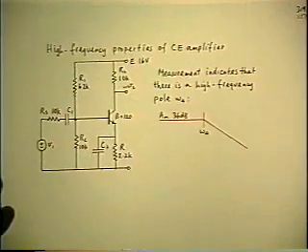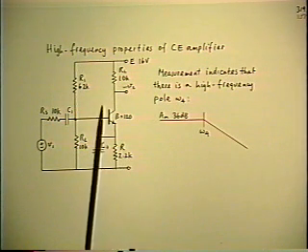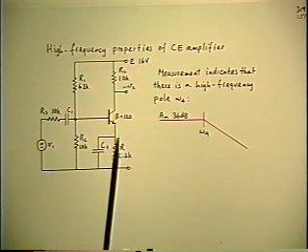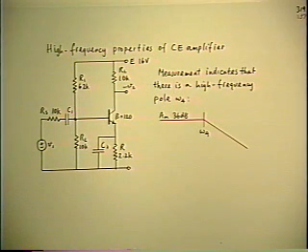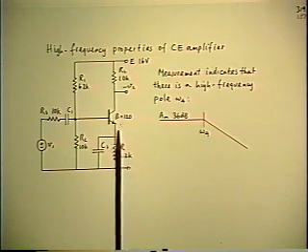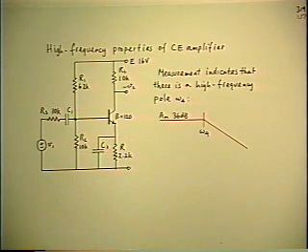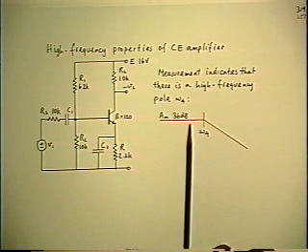The context of this now is, once again, the basic common emitter amplifier stage, the vehicle we're using for all of these examples. I've gone back to showing the full DC and AC circuit here now, with the bias arrangements, the transistor, the coupling capacitor, the bypass capacitor. And we started out by talking about the mid-band gain of this stage, and then we put in the C2, we put in the C1, using the extra element theorem as a convenient way to put those in as extra elements after we calculated the gain at mid-band, which is the AM of 36 dB.